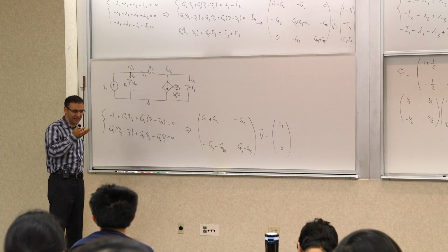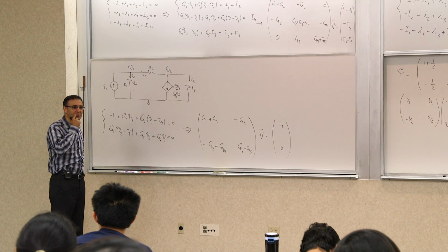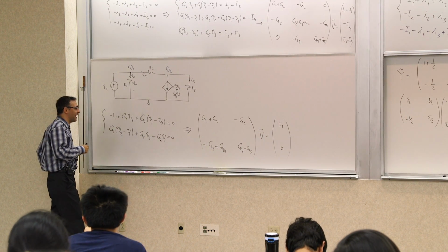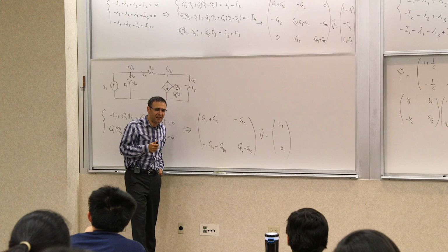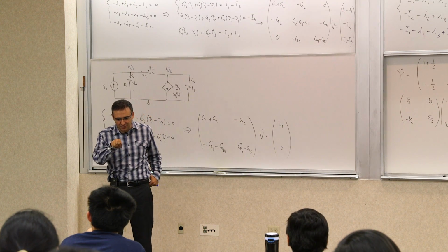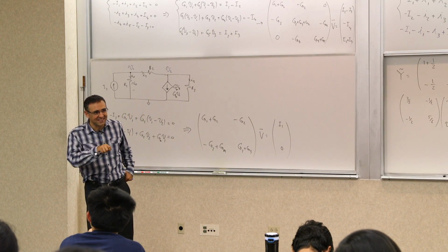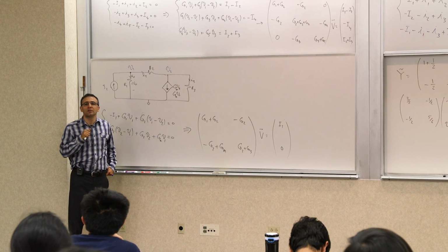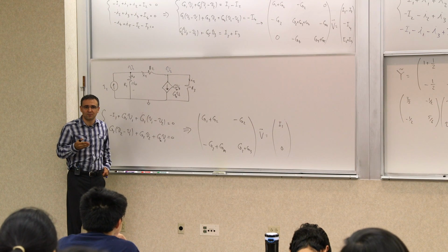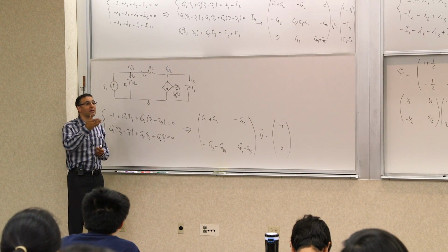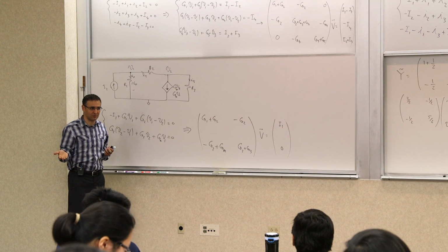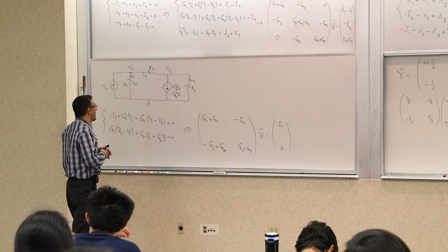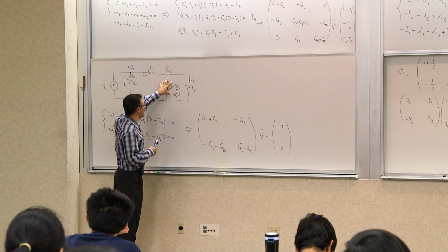There are different ways to do that. I could turn the question back around and say, well, how do you even make an independent source? And then you can say, I make it with the battery. Say, well, okay, why don't you have something that changes the value of the battery, but that's not a really fair answer, right? There are devices, for example, a transistor is exactly what does that for you. A bipolar transistor, for example, is modeled best as a voltage-dependent current source.